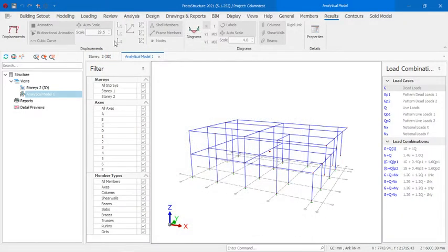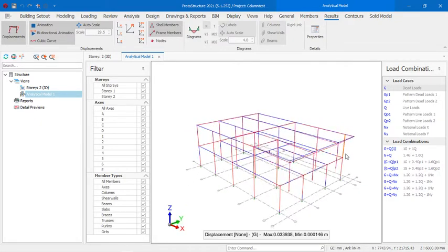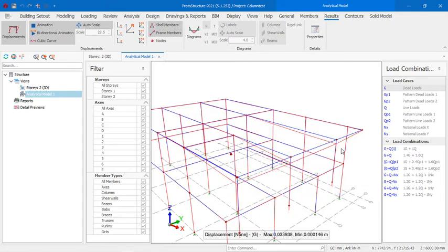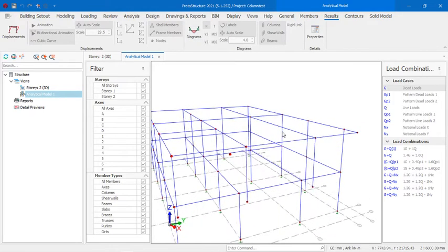Now this is where we are going. If you click on displacement and you see the animation, you can see that the column is dangling. So by that, it means that there is no support. So the moment and whatever forces the software will calculate will be very high in this case, because it's seen as unsupported. I know a lot of people that condemned the software for this, even in the days of Orion, and many people, because of that, said no, they can't use it.